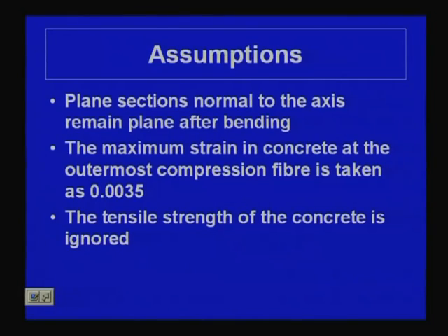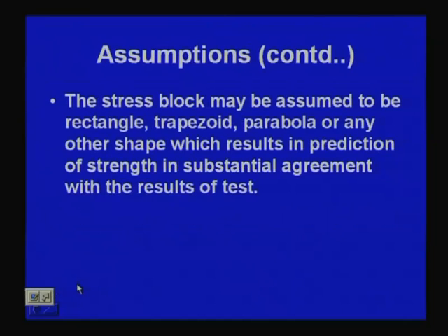The tensile strength of the concrete is ignored. That is almost the primary assumption in our reinforced concrete design. We are assuming that we shall not consider the tensile strength of concrete. The stress block may be assumed to be a rectangle. I shall come within a minute to what a stress block is.